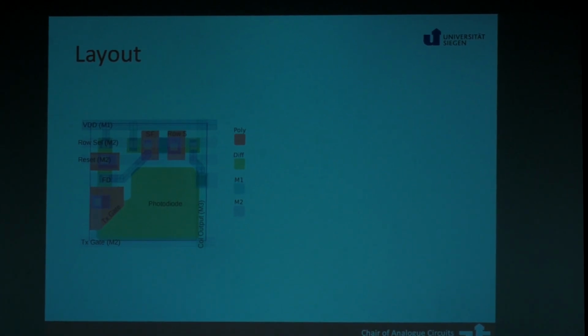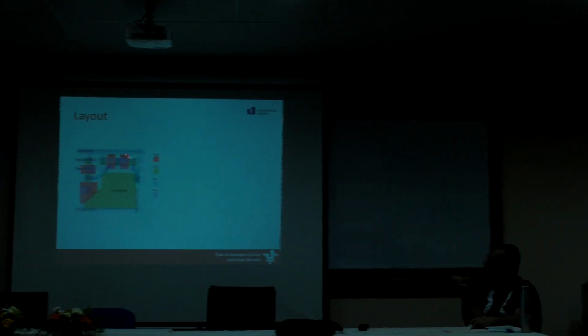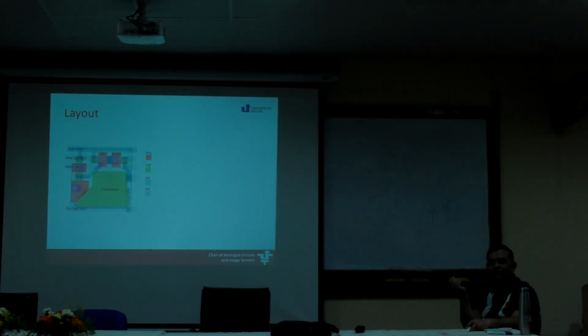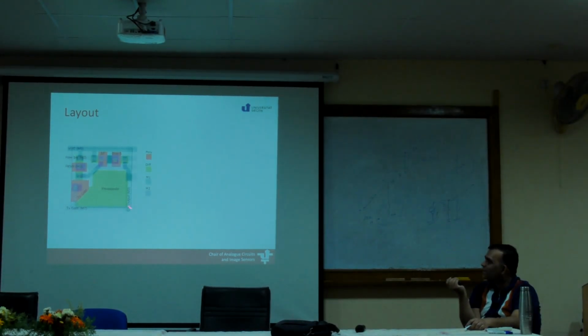So, this is where the square law comes to haunt us. Say the pixel was 5 micron by 5 micron. The area will be 25 micron square. If my diode goes till 3 units here, 3 micron, the diode becomes 3 by 3, okay, I have pushed it here, but if it was 3 by 3, it will be 9 micron square.